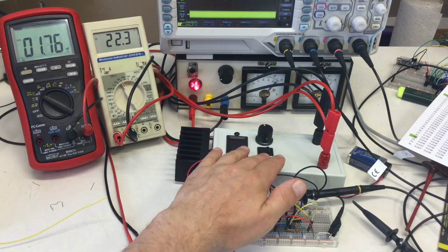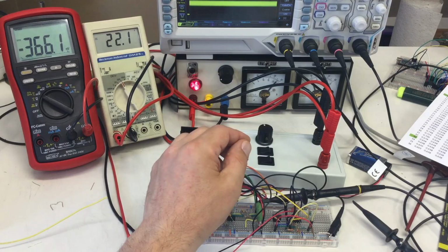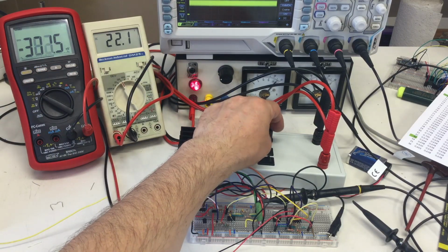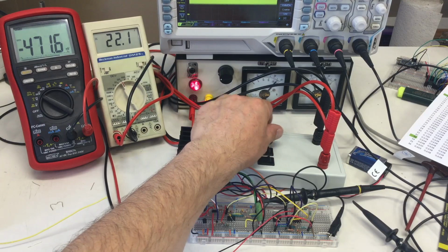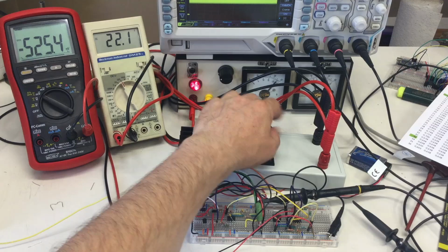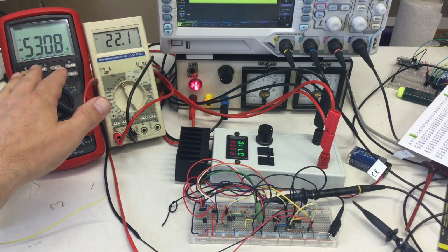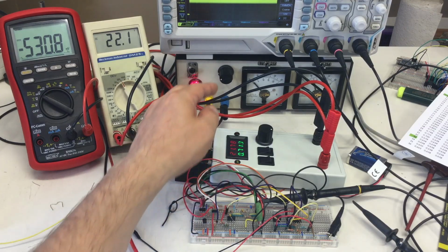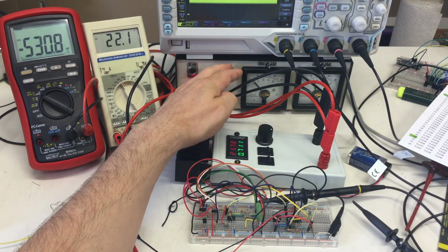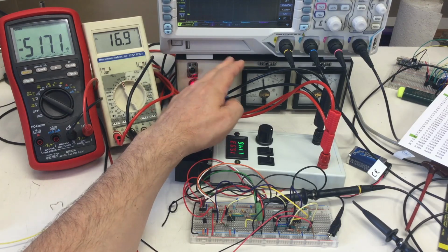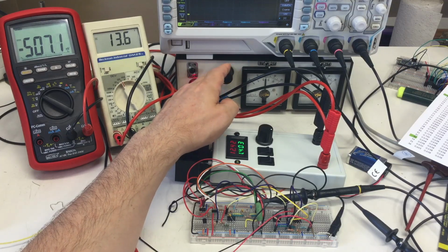Now I switch it on again, and I should again produce a voltage drop, which is now, oh yeah, I turned the pot. Turning the pot a little bit, we come back up to 500 something and we have 700 milliamps flowing. If I now decrease the voltage, the current still goes up. So the op amp has survived.